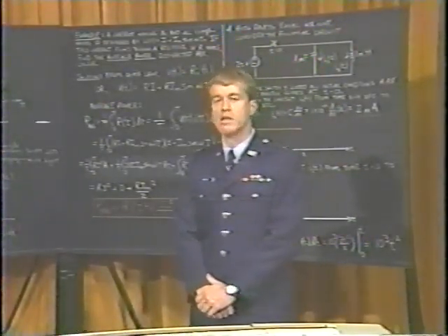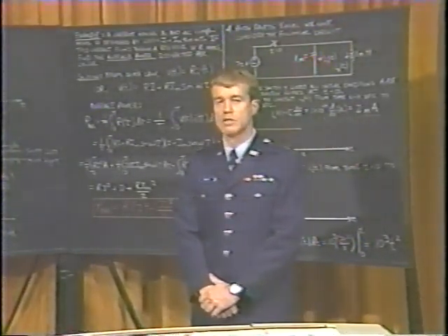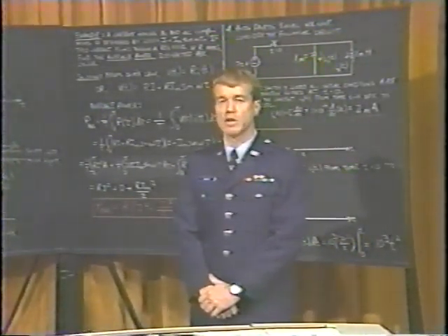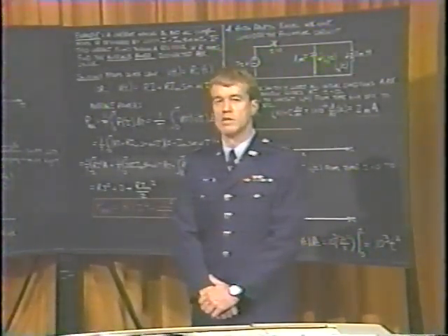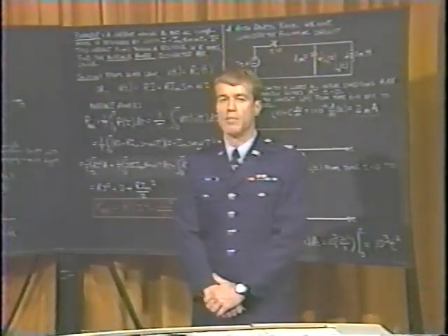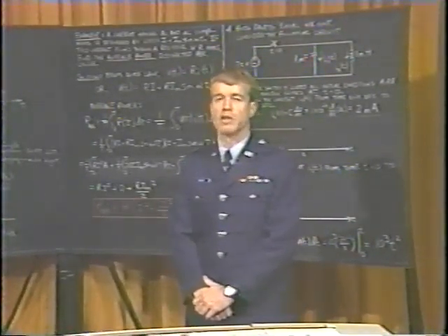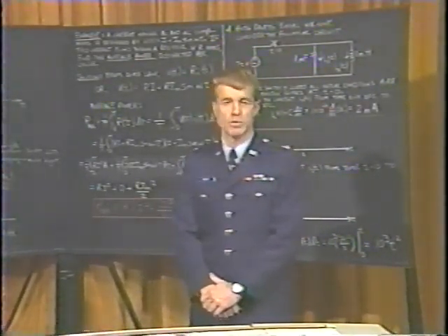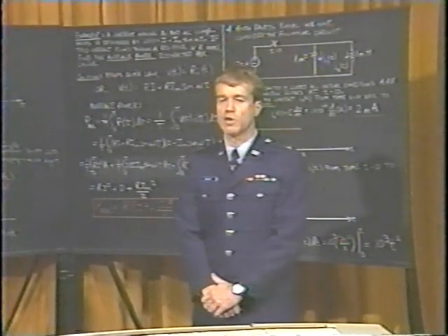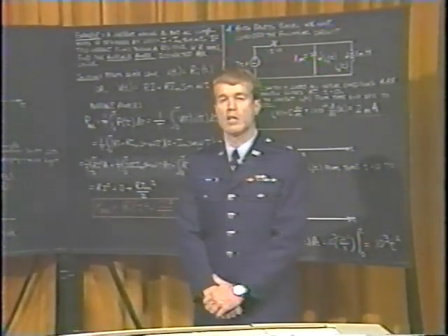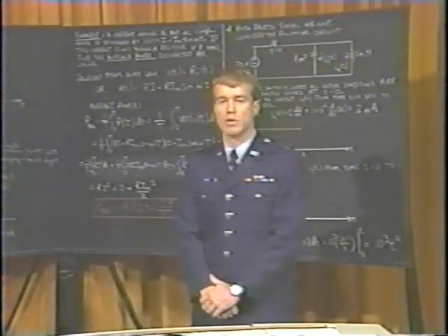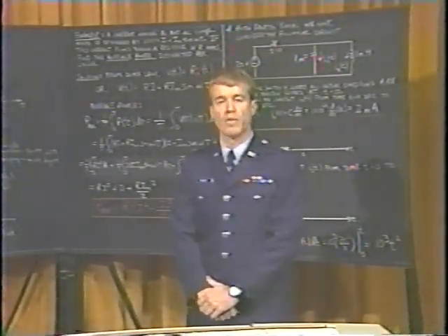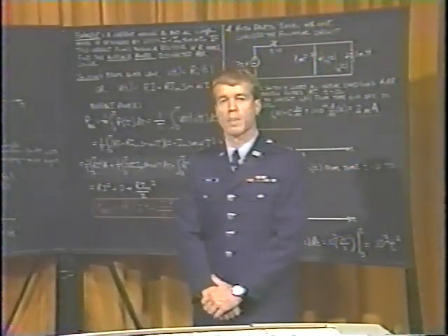And then based on the conservation of charge within any circuit, we arrived at Kirchhoff's voltage law, which told us that the algebraic sum of the voltage around any closed loop in the circuit must sum to 0, and Kirchhoff's current law, which tells us that the algebraic sum of currents at any node within the circuit must sum to 0. These will be fundamental from now on in circuit analysis.